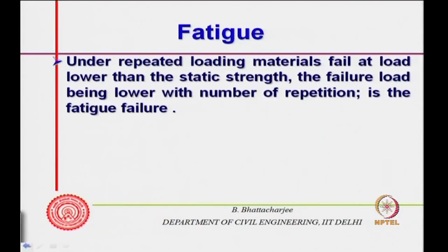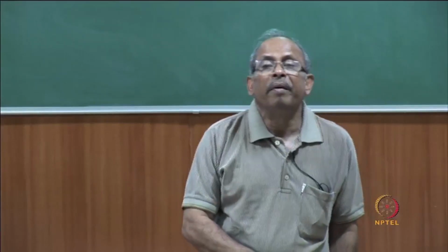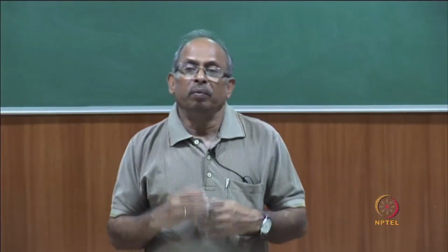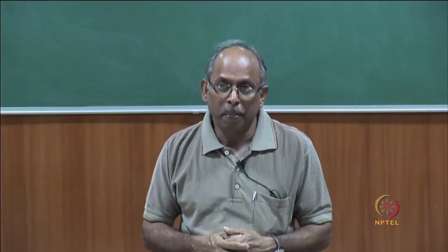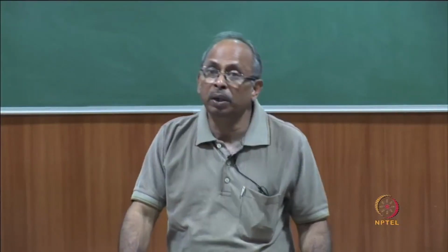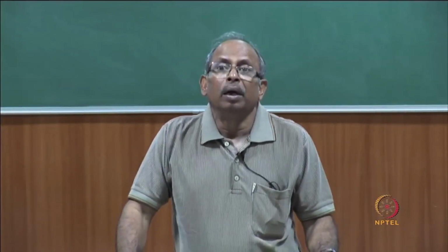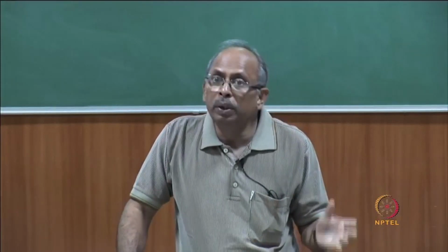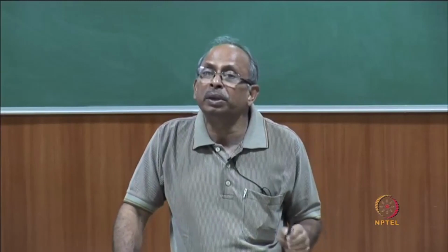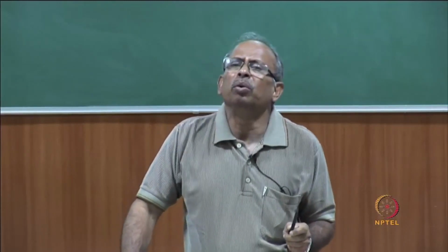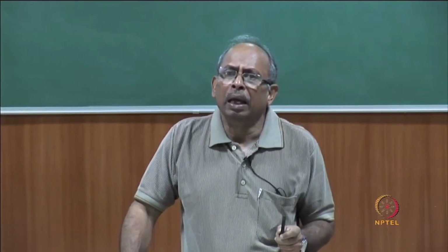Now, let us look at another mechanical property called fatigue. Fatigue is related to reversal of stresses, and you can understand the importance of this in many structures. The imposed load applied in most structures is actually quasi static, and we do not call it fatigue.